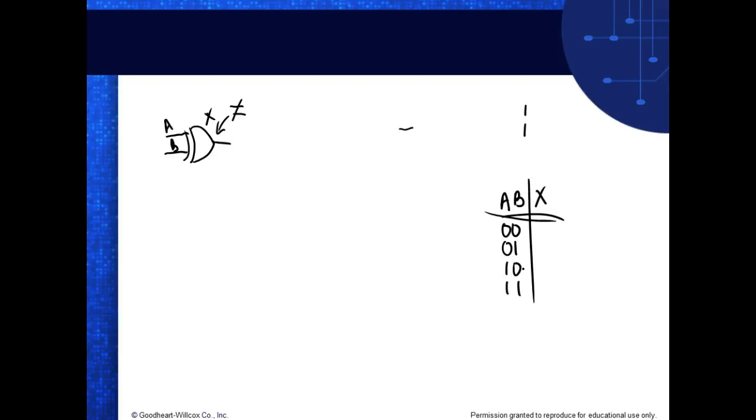It's also a problem with Karnaugh maps, because for every combination in a Karnaugh map, you've got to have a box, right? I think y'all learned Karnaugh maps. Truth tables are good for teaching logic, and Karnaugh maps are good for teaching logic, but you need to learn Boolean algebra. With Boolean algebra, you set up a math equation for a circuit and then you try to reduce it. What's nice is that if you can reduce the math equation, you're actually reducing circuitry, right? Does that make sense?